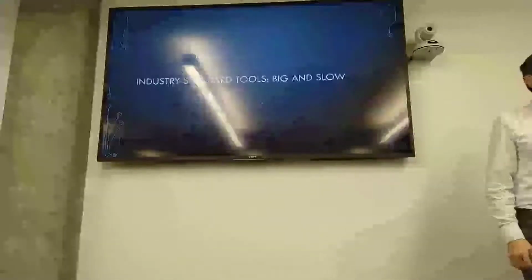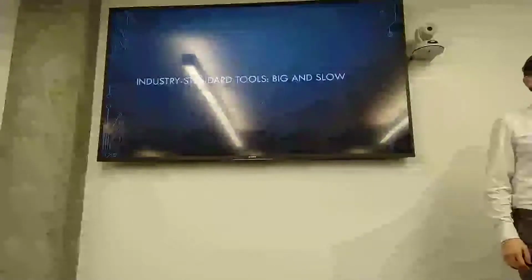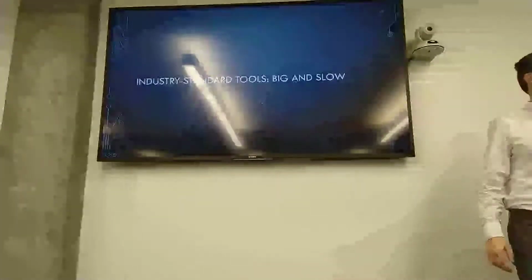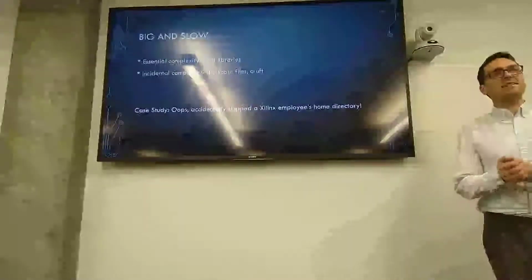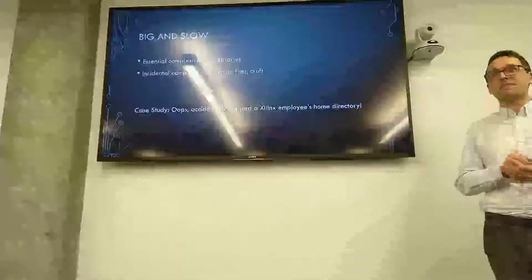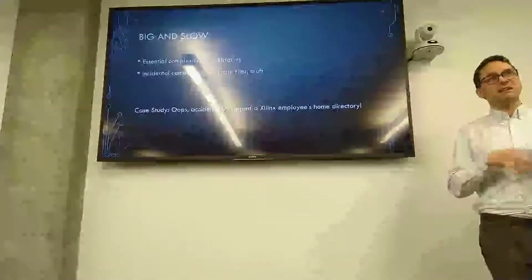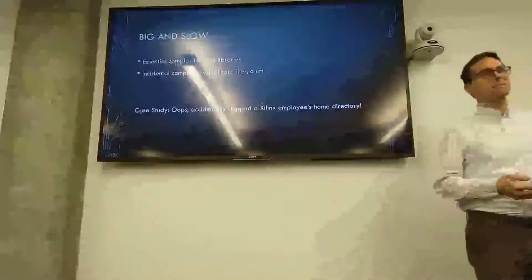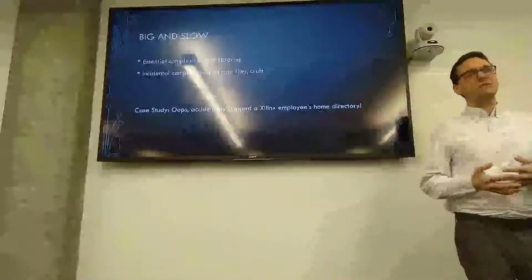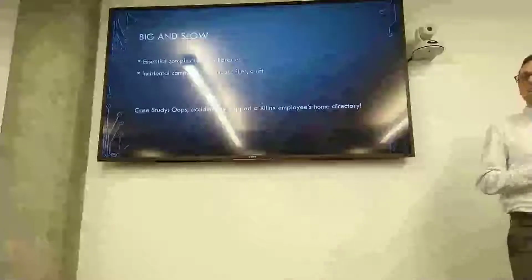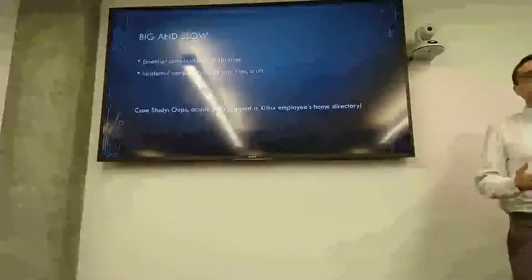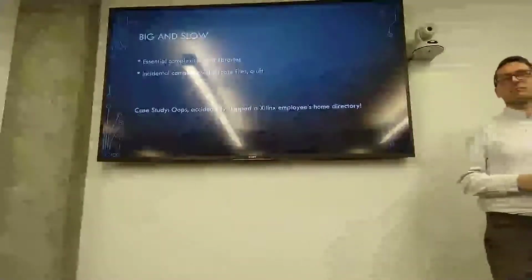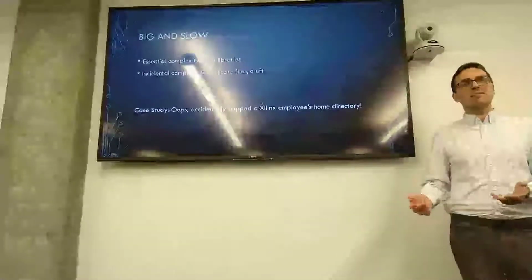First, the problem. The industry standard tools, as anybody who's used Vivado knows, are very big and very slow. Some of that is because of essential complexity. The tools themselves have to do a difficult job of understanding all the different FPGA designs, doing place and route, the NP-complete problem, and there's also some internal or incidental complexity. Like the tools have lots of features, not necessarily features you want, but the features that some customer asked for and are in the product anyway.